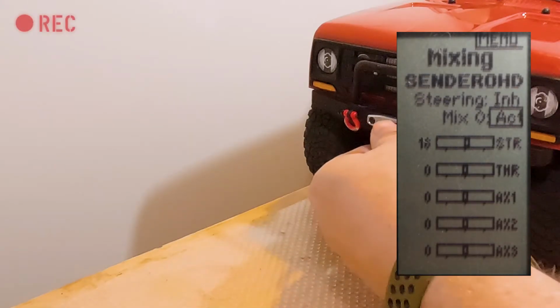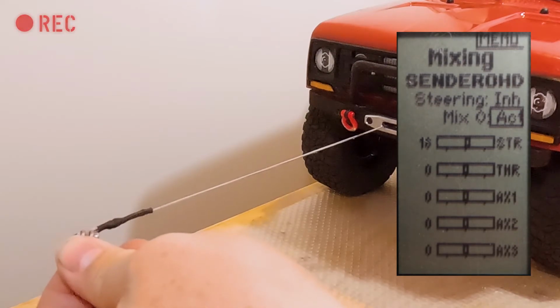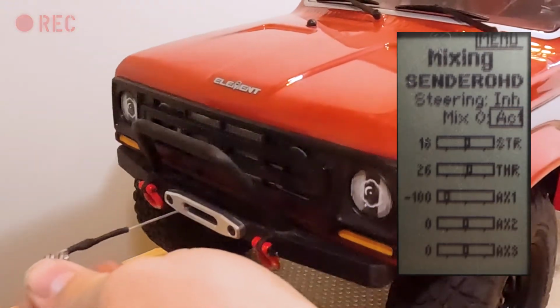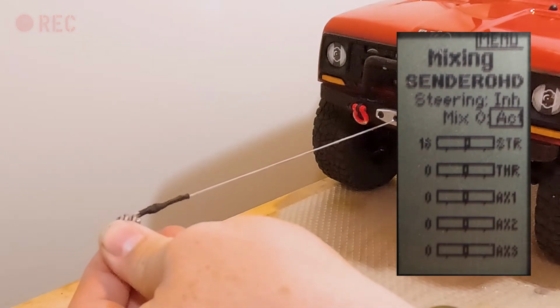When mixing is enabled and you spool the winch line in and out, the truck will drive forward or backward at the same time. Pretty neat, huh? But the real cool part is that should you need the truck to momentarily move slightly faster or slower, for example, due to variations in the terrain, you can simply pull or push the radio trigger to feather the throttle rate.